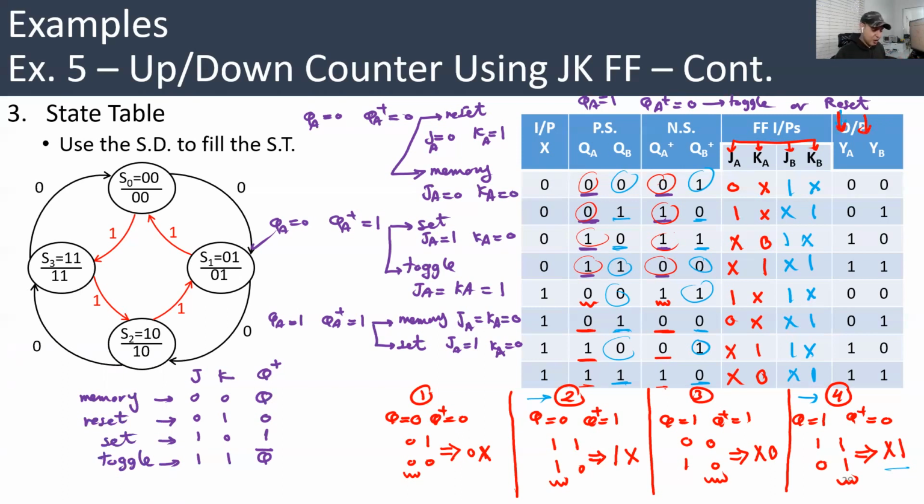6, but luckily we know that YA is equal to QA. This is from the last lecture. When we solved this design using D flip-flop, we knew that YA all the time equals QA and YB is equal all the time to QB. So you are just going to save 2 Karnaugh maps now. Now you just do 4 for JA, KA, JB, KB. So let's do this.